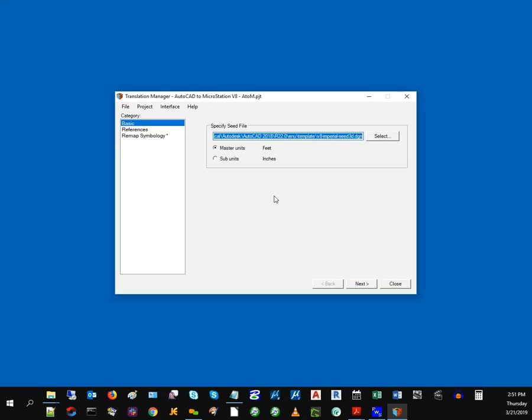That made it very, very difficult for them to clean up and make the files into some easily usable form on the AutoCAD side of things. And there's one setting in the MicroStation translator that gives you the ability to take those instances of the same cell and form them into a shared cell, so that on the translation side, it just becomes a block definition that then has block references to the places where that cell was placed.